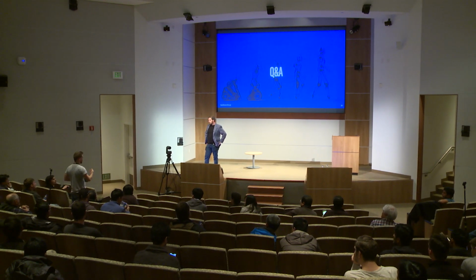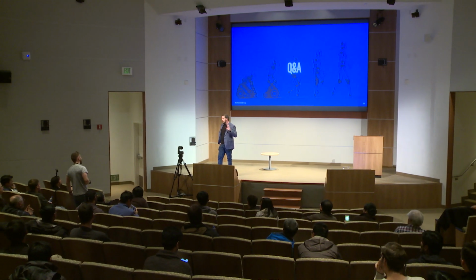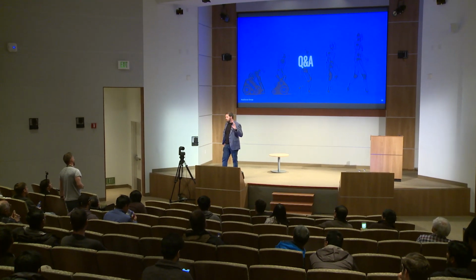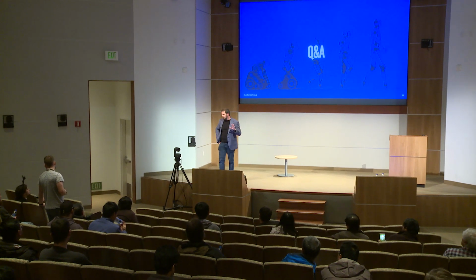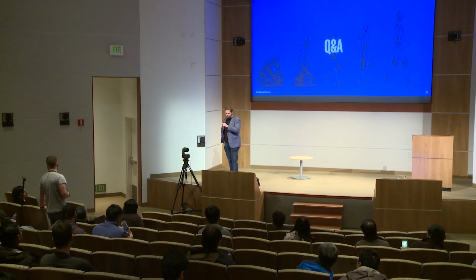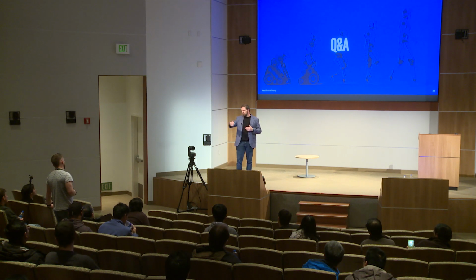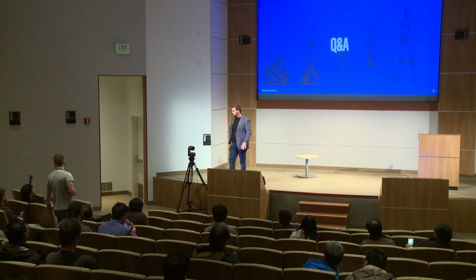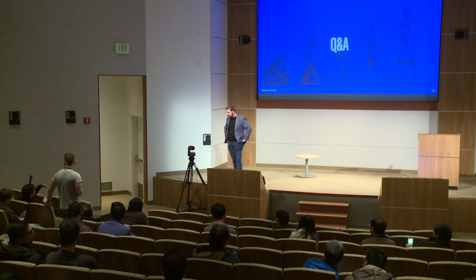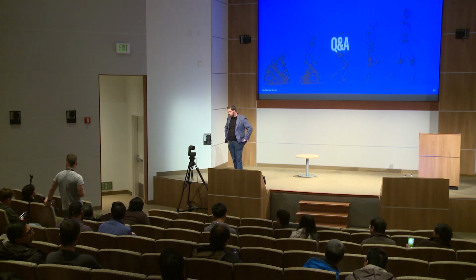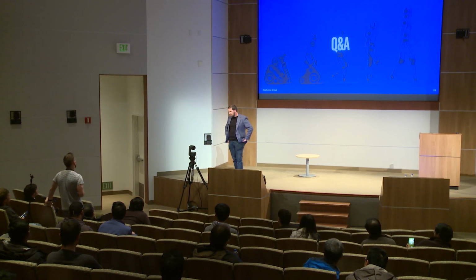So for the dense depth, we use the depth camera D435. You're right, for the tracking camera, we also have a stereo system. We are also able to estimate the depth or the distance of points. But in that case, as I mentioned, we're using a sparse algorithm, so it's only very few points. So it's using the vision to understand distance to objects, right?